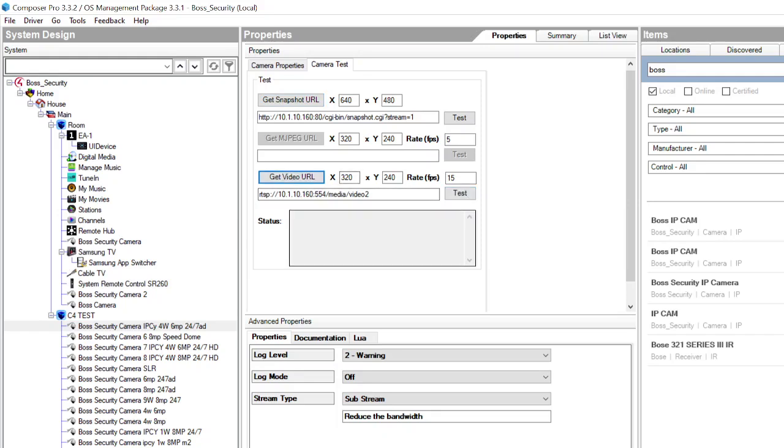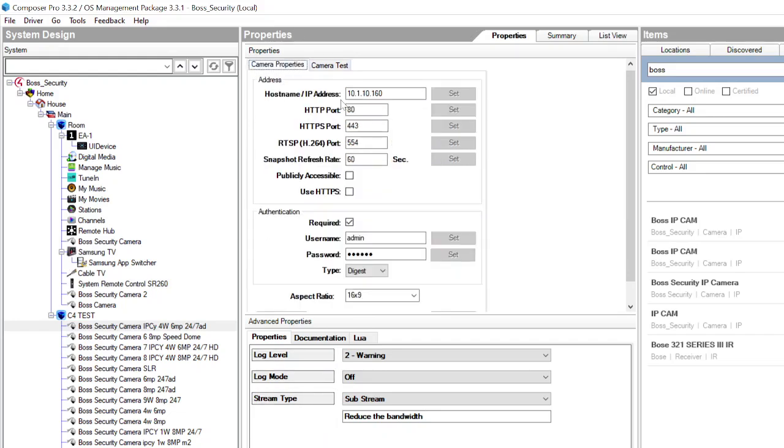If they do not pass and they fail for the frame rate, you're going to need to go into the camera GUI through your web browser through that IP address, and you will need to downgrade to match that. Like I suggested before, either use the substream or the third stream.